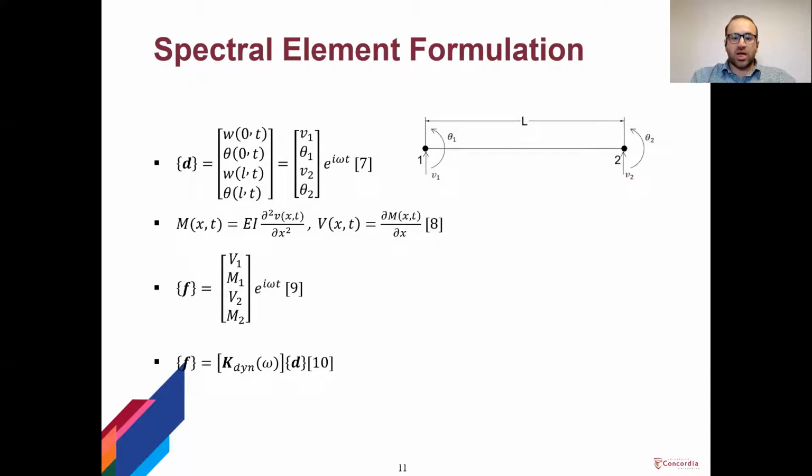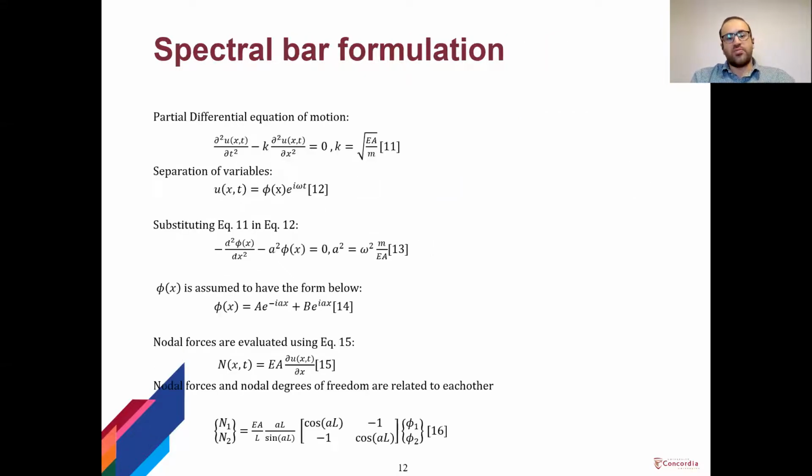So nodal forces are calculated according to equation 8, which shows the force-displacement equations. The matrix that relates nodal forces to nodal degrees of freedom is called the dynamic stiffness matrix, which is a function of frequency. So the same procedure can be followed for the spectral bar formulation.